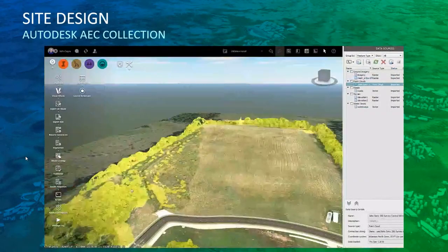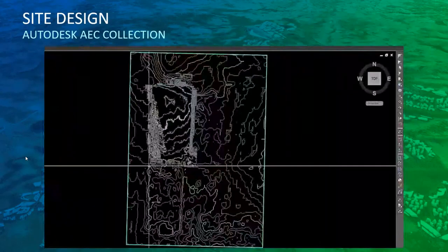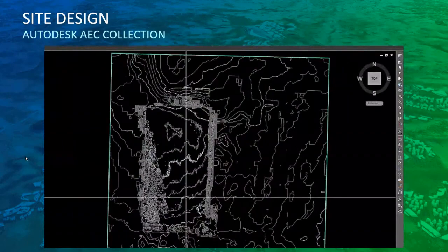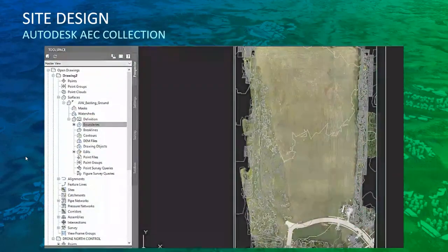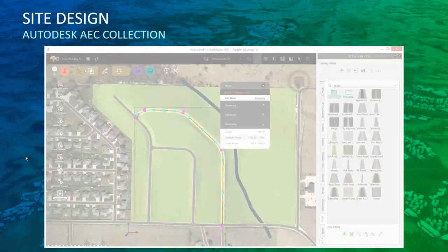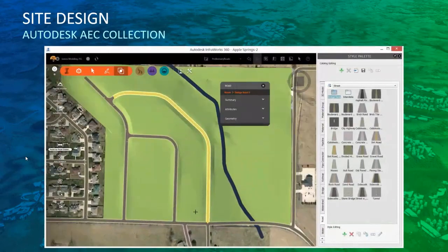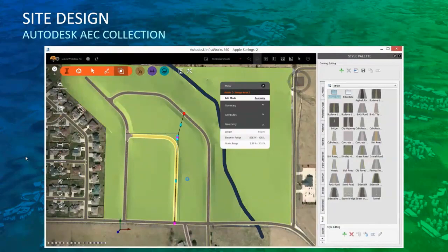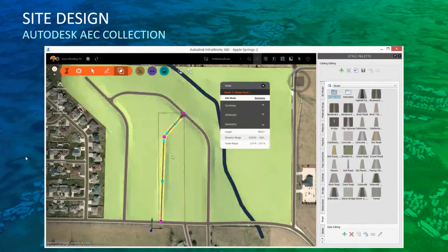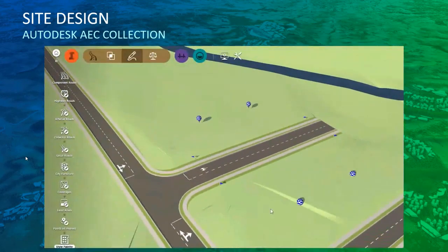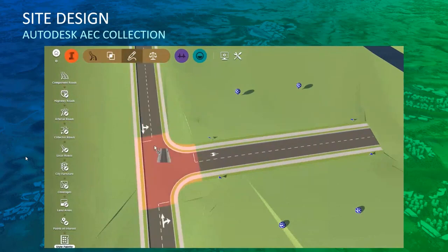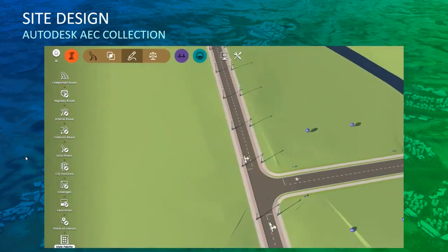model and generate a more detailed terrain surface. With a more accurate model of your project in Infraworks 360, you can now take the surface model and conduct preliminary design layout. You can start laying out your preliminary subdivision concept, beginning with road designs in your subdivision in both horizontal and vertical configurations that adhere to engineering standards. You're able to use analysis tools to check for lot spacing and build a road styling to help determine lot